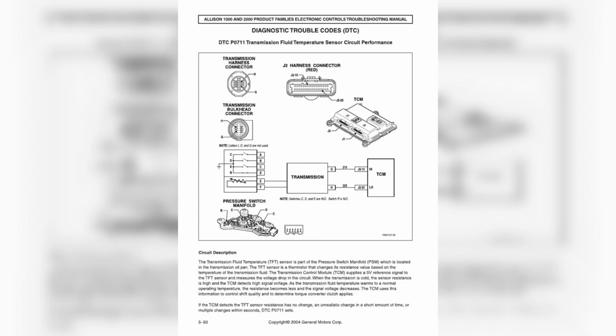Careful inspection of wiring and connectors. Repair or replace defective sections. 3. Inadequate transmission fluid level.